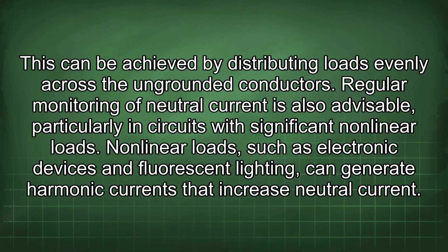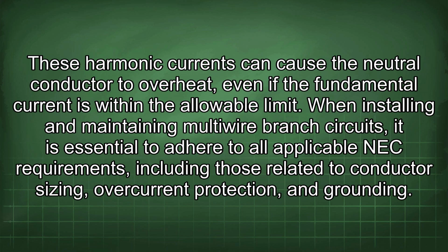Regular monitoring of neutral current is also advisable, particularly in circuits with significant nonlinear loads. Nonlinear loads, such as electronic devices and fluorescent lighting, can generate harmonic currents that increase neutral current. These harmonic currents can cause the neutral conductor to overheat, even if the fundamental current is within the allowable limit.